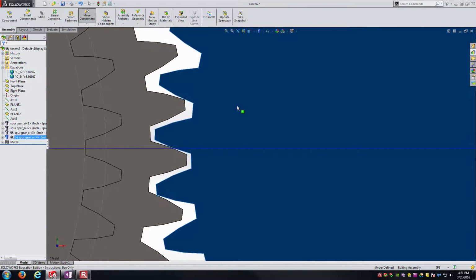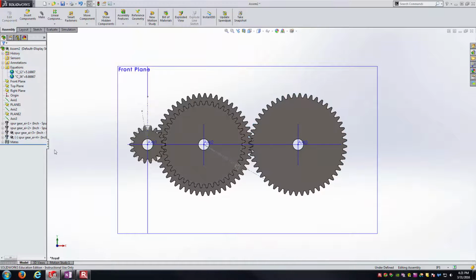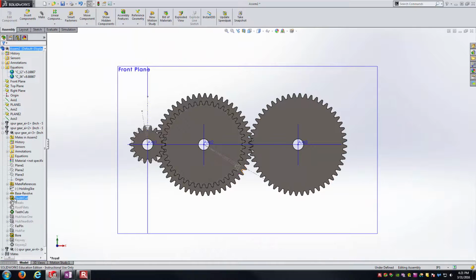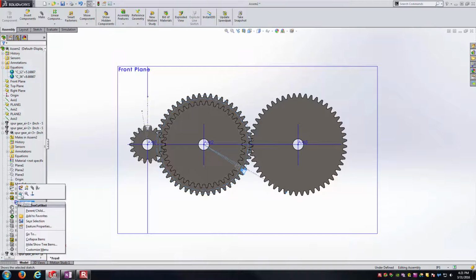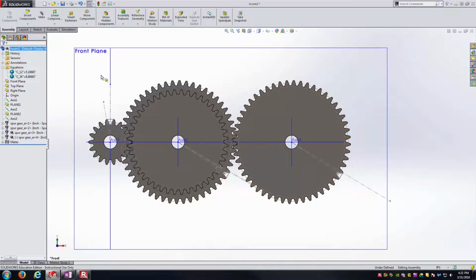And so here again, I'm going to position it so that the teeth don't interfere. And I need to show some sketches again. And so here, I'll go ahead and show the tooth sketch of my third gear. And now of the fourth gear, drilling down and doing the same thing as well. Or I guess they're the same exact gear, so it picked it up automatically for us.